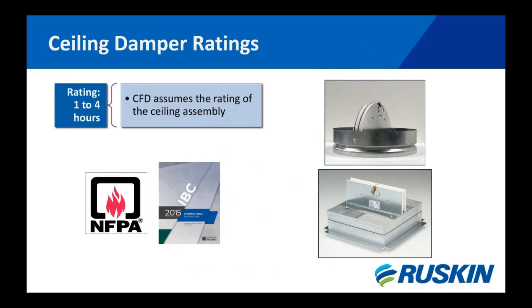So as I said earlier, the UL sticker will just reflect ceiling dampers, and so we can go from 1 to 4 hours depending on roof assembly or floor assembly type. Your wood construction is usually limited to 1 hour, and non-combustible floor ceiling systems made up of steel joists or metal decking and concrete upper cord is usually going to range from an hour up to 4 hours depending on the components that are in that assembly.